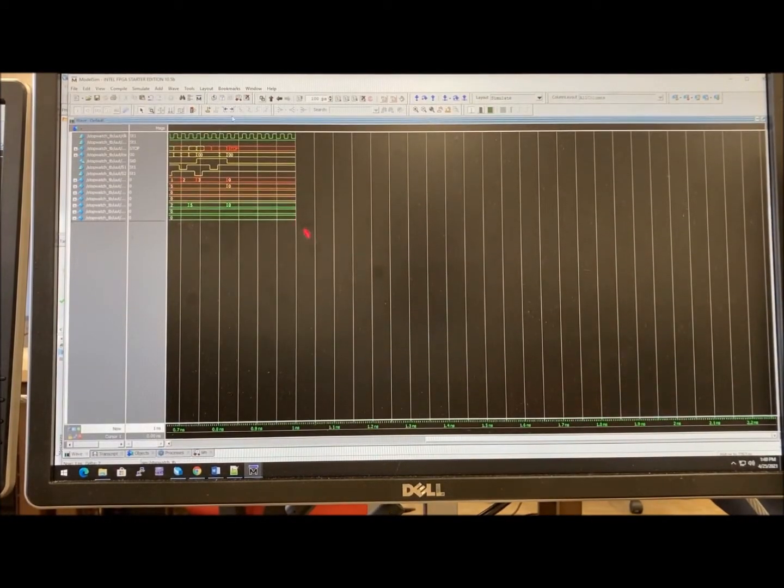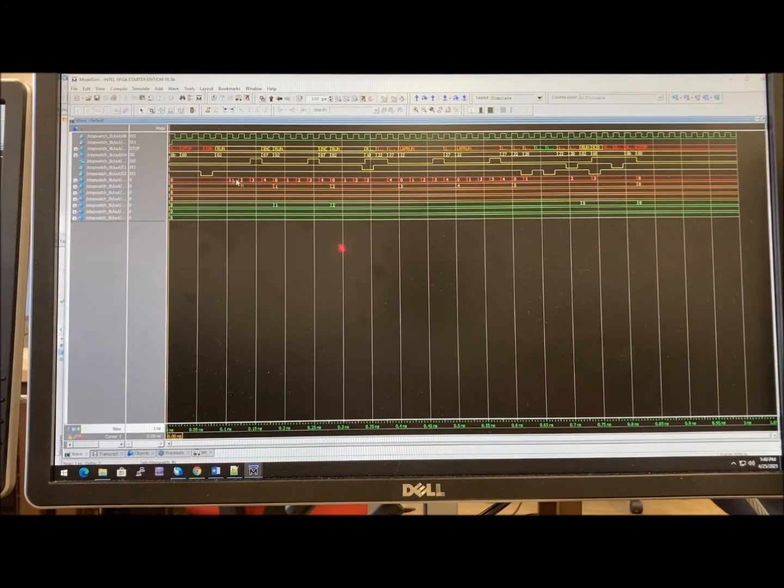An important thing here: if you did this correctly, you'll notice multiple tenths here. However, if you don't notice any tenths at all, that likely means that the time constant that you count up to in your data path has not been adjusted. There are two values we use there. There's 3, which is great for test benches, and then there's 50 million, which is used when we're actually using the board and we have an actual frequency input of 50 million.